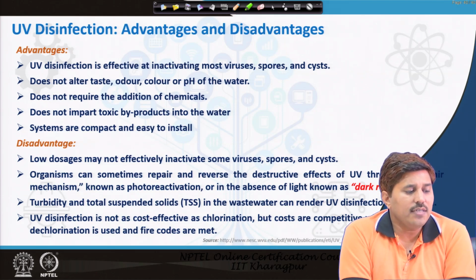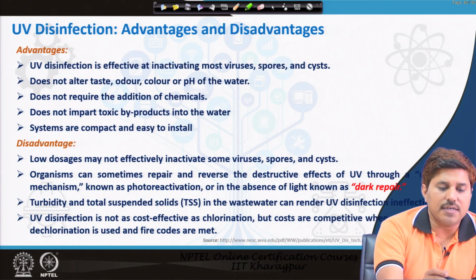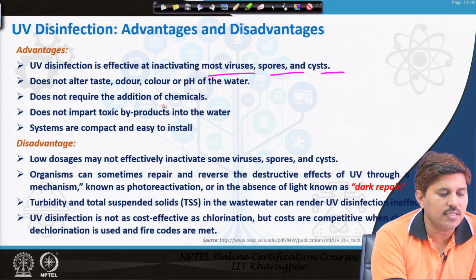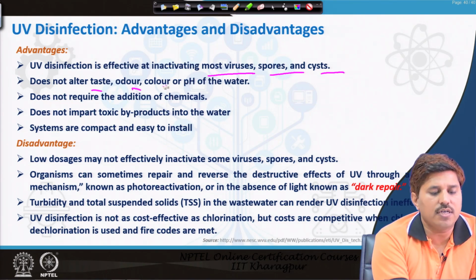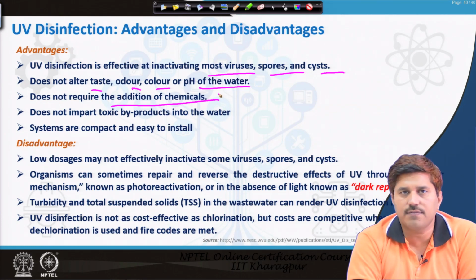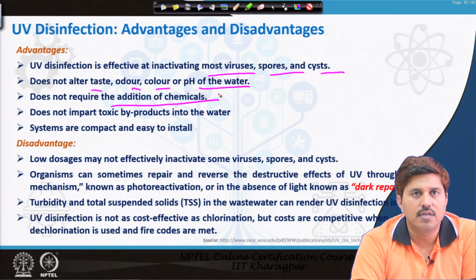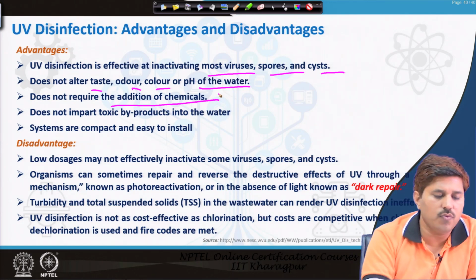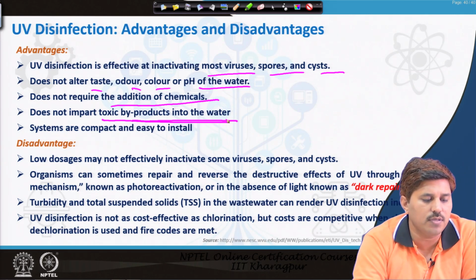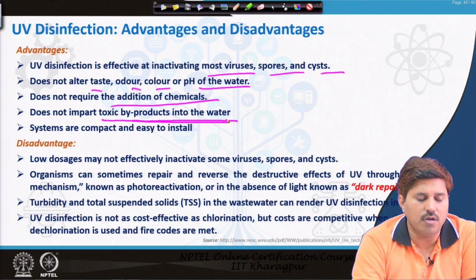On the advantage side, UV disinfection is effective against inactivating most viruses, spores and cysts. It does not alter the taste, odor, color or pH of water. It does not require the addition of any chemical, not even ozone or a gas form chemical. It does not impart any toxic byproduct to the water, so that is another very important advantage. It does not produce byproducts. Systems are compact and easy to install.